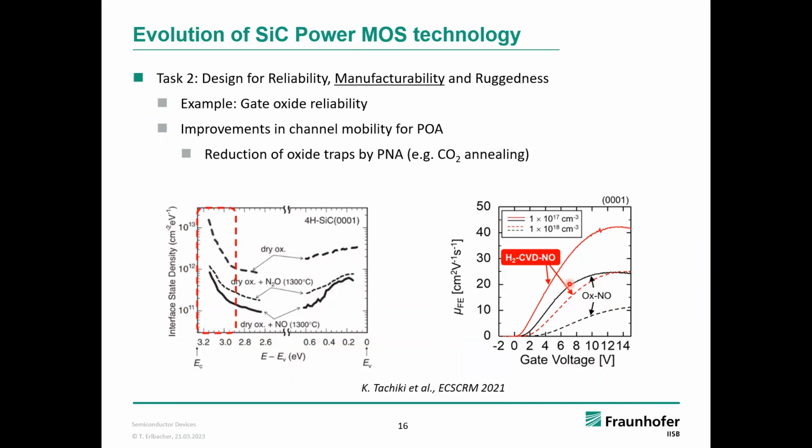While in silicon, everybody knows you make a 900-degree oxidation in a forming gas anneal, maybe something with chlorine in there, and you can readily buy equipment where the equipment vendor will already provide you with a nice recipe for that. We're basically talking about the 1980s in silicon for silicon carbide when you compare it to silicon technology.